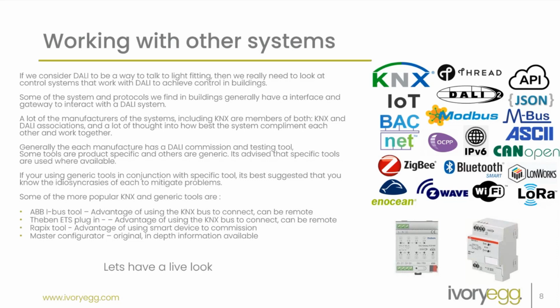If you're using a generic DALI tool in conjunction with a specific tool, it's best suggested that you know the idiosyncrasies to mitigate problems. So you really must know or speak to someone before you go operating a generic DALI commissioning tool in conjunction with the dedicated or specialist DALI commissioning tool for that product, and then we can get around things.